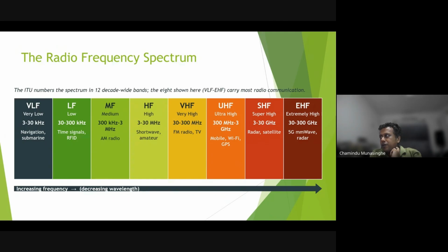Also, when you use lower frequencies, we have to be wary of the bandwidth. With low frequencies, you can't transmit a lot of bandwidth. That has to do with, if you have studied the Nyquist-Shannon sampling theorem, the amount of data that can be encoded is directly proportional to the sampling rate. So with low frequencies, the bandwidth that you can use gets reduced as well. That's why we are bandwidth conscious when using lower frequencies like HF.